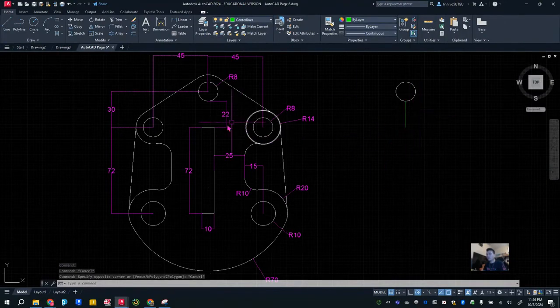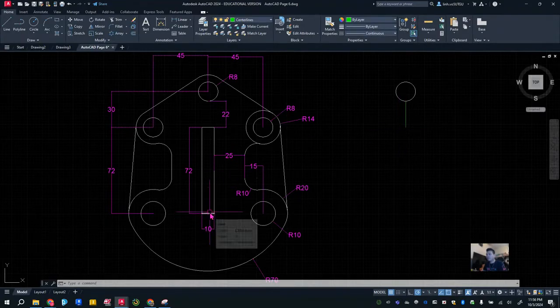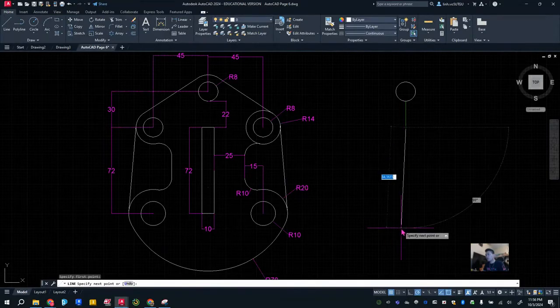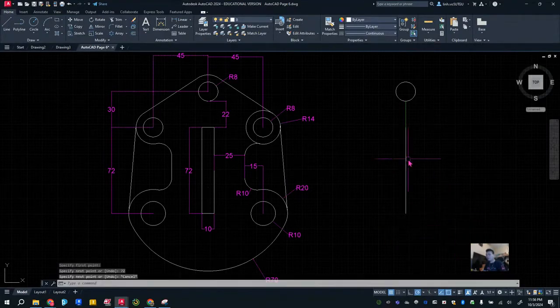All right. Now, when we are down there, we are exactly at the center of this, right? So I'm going to go into my construction. This right here is 72, so I'm going to take that down 72. And then I'm going to take offset, because right now what I'm drawing is right in the center of this.